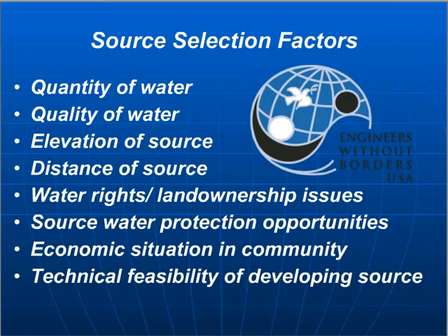The economic situation in the community is really important, and when I review projects, and I've probably done 500 reviews since I started working here, I think one of the most common oversights for teams is to not consider the economic situation until they're later on in the design, and so they end up with a solution that the community simply cannot afford to maintain, let alone make any kind of repairs or upgrades, but to simply pay the electric bill, for example. If you're designing a project that requires pumping, you would need to know up front, before you get very far, as you're in your source selection process, the first step of a water project, you need to have some sense for what the community could afford to pay to know what kind of electric bill you could even consider as part of your project.